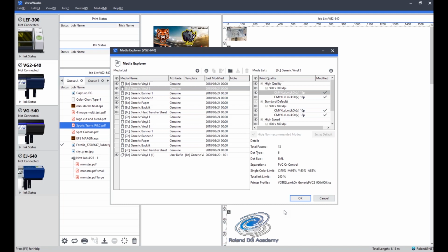But this is talking about calibrating the machine to its default settings, so that over time with deterioration or change in parts, say you had to change a print head, if you've got a multiple print head machine, you're just recalibrating it back to your default standards so that over time you're still getting the same output from your machine. When it comes to calibrating profiles or your machine to a certain color standard, yes, I think in theory, but the color match settings are slightly different to calibrating it to a standard. I hope that makes sense.